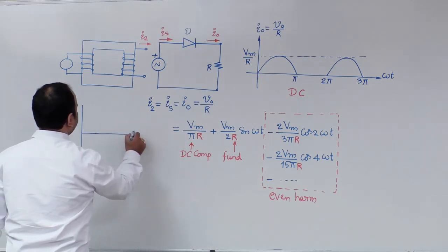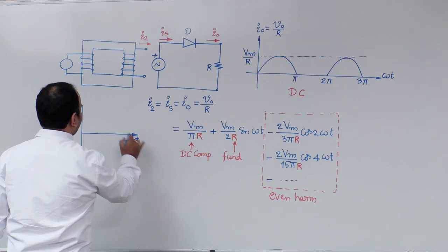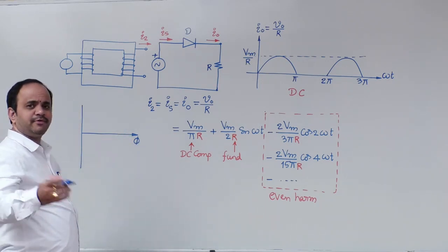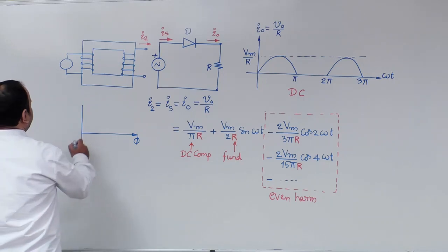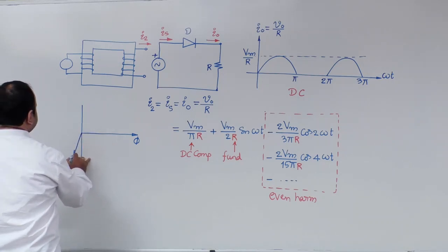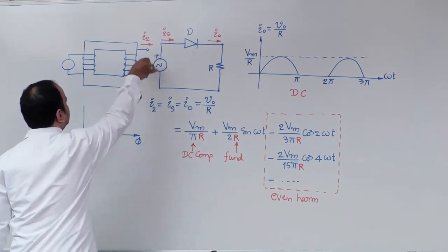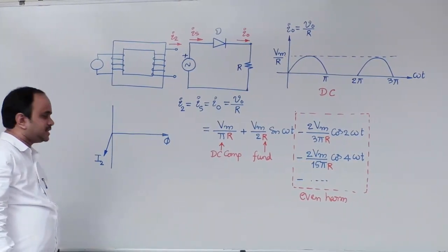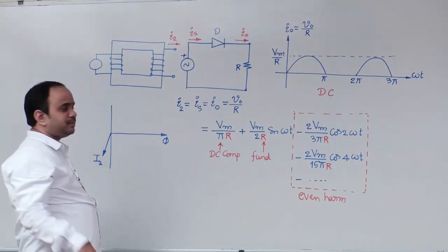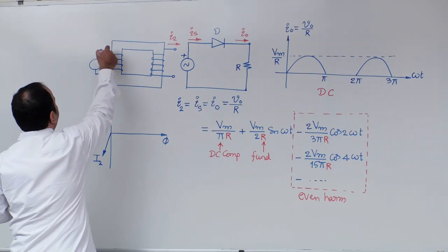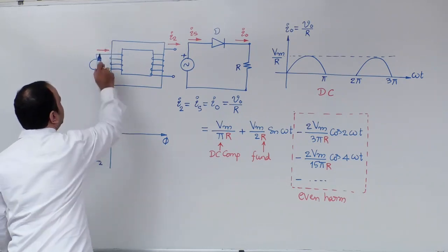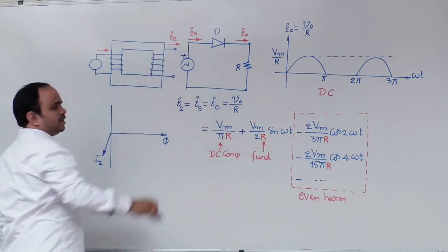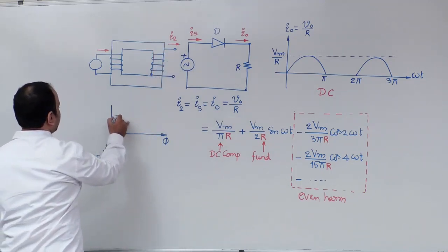But you might have studied in the transformers course, what is the basic concept of a transformer? A transformer operates on the constant flux or MMF balance concept, right? That means whenever a load is connected, some I2 will be flowing in the secondary side. As per the transformer concept, the primary will supply balancing for every sinusoidal component of I2. So you can draw it in this way.